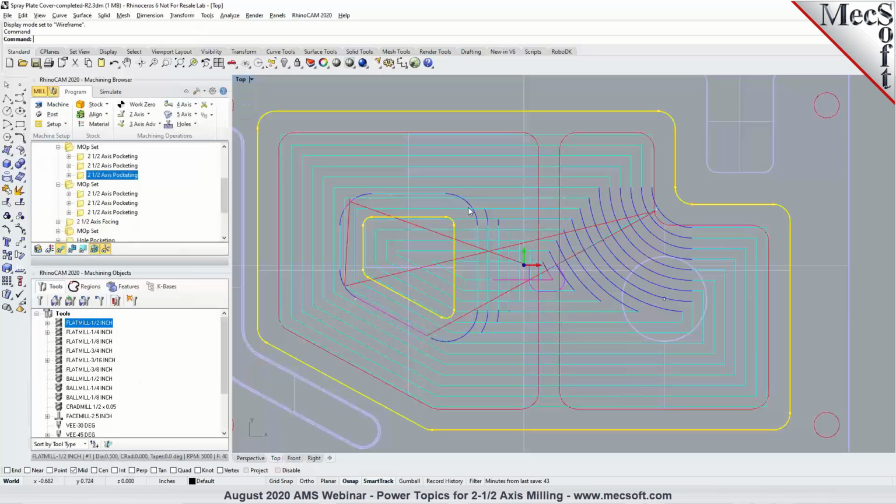So this will give you the best result for arc fitting, where splines or polylines are fit to arcs wherever it's feasible. And the reason we recommend 2 times is to avoid tolerance stacking. So arcs can be fit to toolpaths, and you can specify the arc fitting tolerance. So this gives you an overview of how tolerance affects your machining in 2-axis operation.